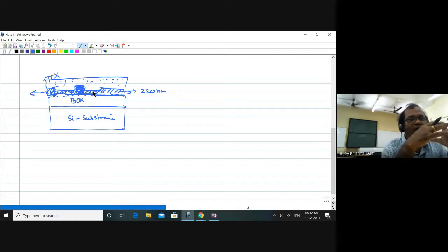But what I was trying to mention, about quantum dot. In case of waveguide, if photon or light is confined in three directions, then it is called resonator. Okay, waveguide resonator, you know, in microwaves, you know that three-dimensional confinement square box you can consider as a resonator. So here, since photon is allowed to confine in a small region, to submicron cross section, that's why it is called photonic wire. It is not quantum wire, it is a photonic wire. Photon within something like quantum wire, that is photonic wire. So you should not misjudge. That is basically optical waveguide, but with small cross section.